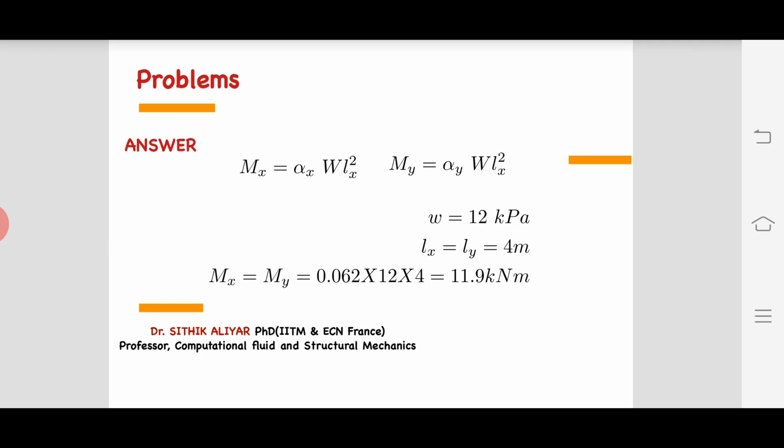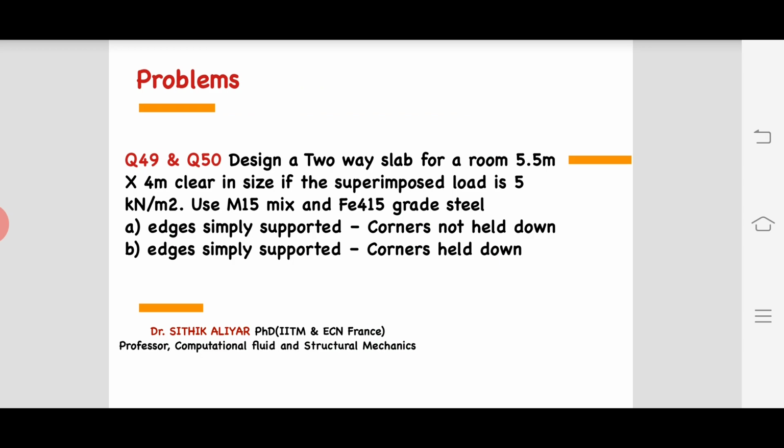I hope you memorize this number. See, the bending moment is only 11. In a singly reinforced beam, you have seen bending moments of 60, 70, 80, 90. Doubly reinforced, you have seen 150, 200, 250. Flanged beams reached 250, 270, 280, correct? You should understand the slab bending moment range. When you are solving some problem, whether in a semester or in any exam, if you are getting an answer of 100, no, your slab cannot have 100, obviously. The slab answer should be in the range of 10, 20, maximum 30 itself, a very big number. So have that in mind.